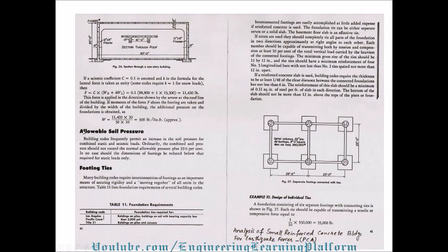This is another important aspect for the foundation design: the seismic coefficients and other factors to be considered when we are designing reinforced concrete structures. The interconnection between the footings is provided by plinth beams as well as tie beams where the earthquake forces are very high.